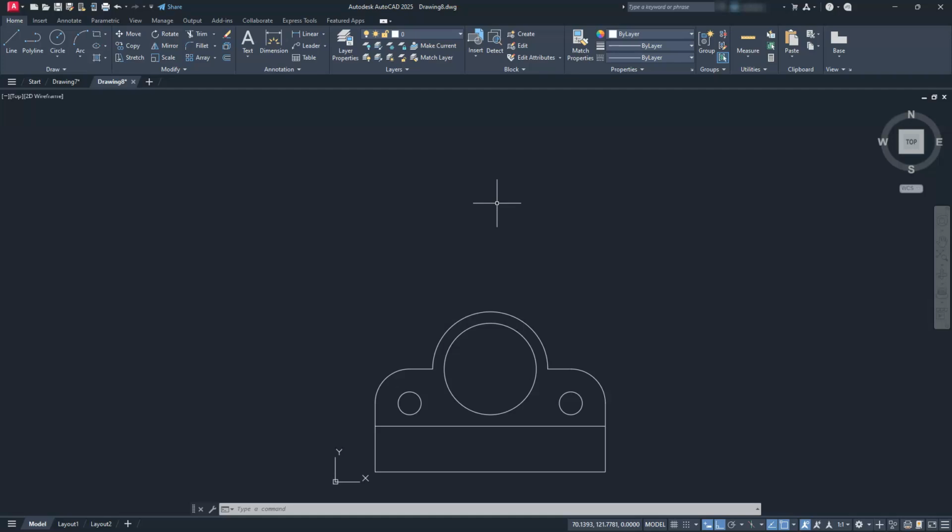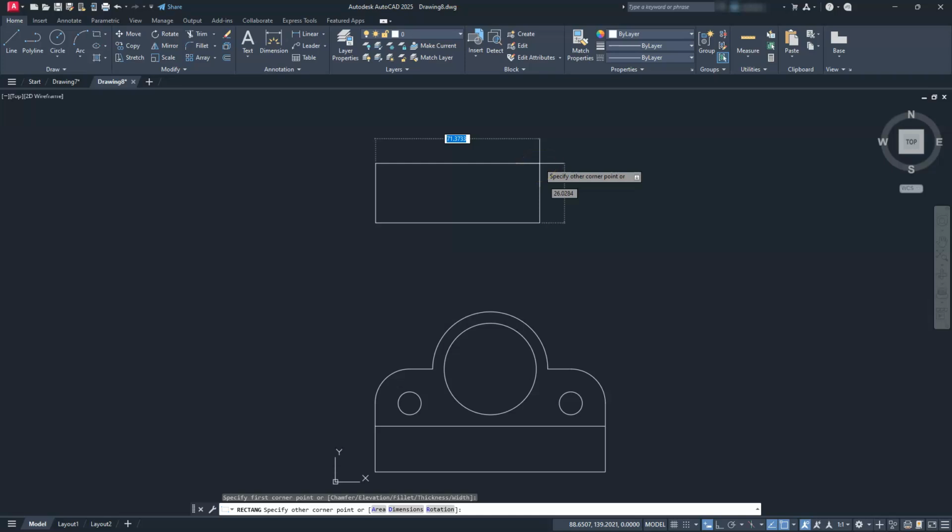And we broke this down in depth on that 3D AutoCAD video. So if you want to go and take a look at that, you can see a complete breakdown of this one. But I'm just going to start off with a rectangle. I'll go ahead and touch, do not click on it, and then track up from it. And I'm just going to give it some distance. That looks good to me. I'll do a left click here, and then I'll type in its coordinates, 100, 60.